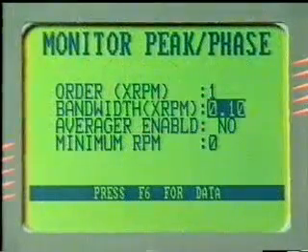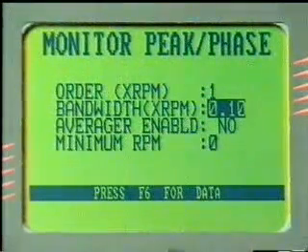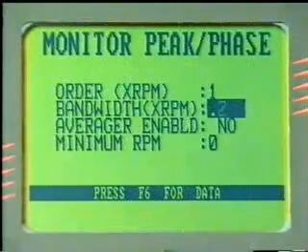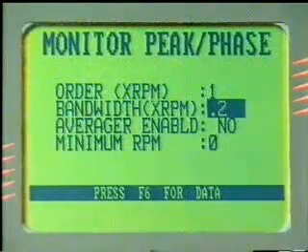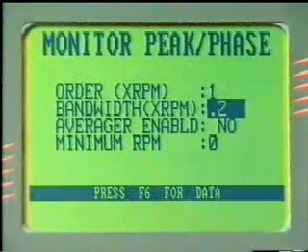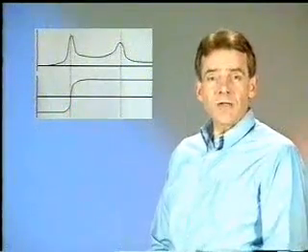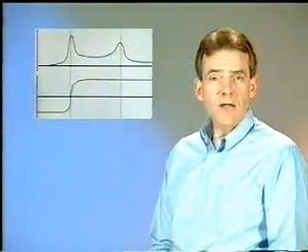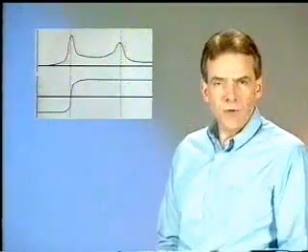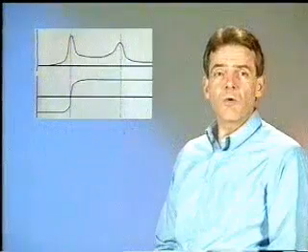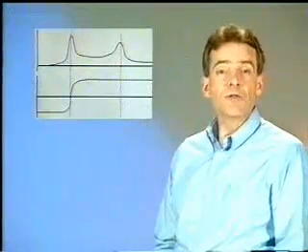To collect good phase data without holes or gaps for machines with quick startups or coast downs, increase the bandwidth to get faster samples and data. Phase data from transient conditions, such as coast downs or startups, provide information about resonant conditions and frequencies that may be difficult to acquire by other means. This information can help you in determining appropriate operating speeds and residual unbalance.